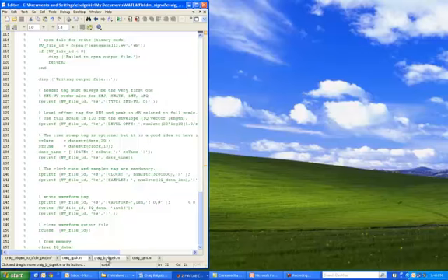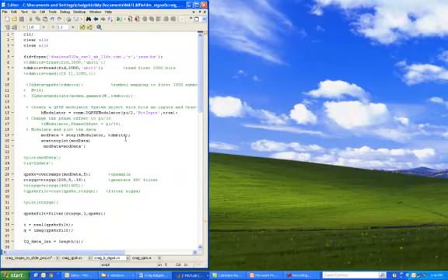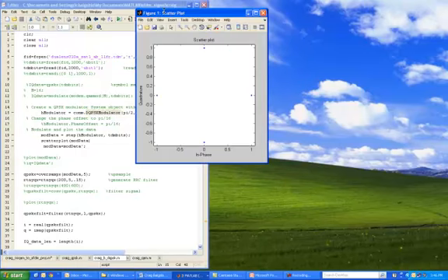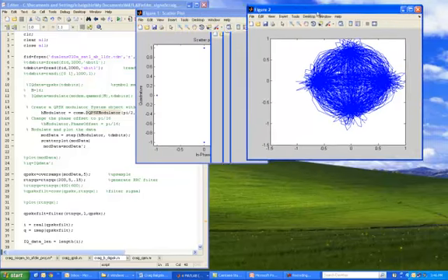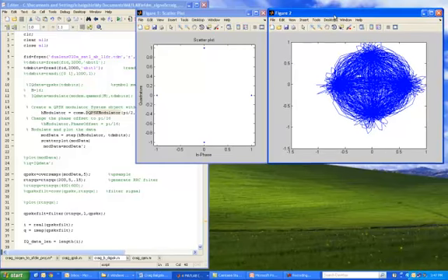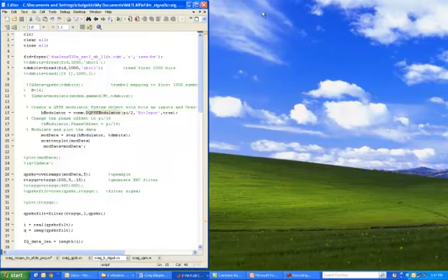Okay, so after I did the QPSK, I experimented with differential QPSK using MATLAB's differential QPSK modulator. Simulate that. So as you see, the scatter plot is a little different. It's phase shifted. Now the reason it's called differential is because it's looking at the difference in the QPSK symbols and then plotting a quadrant. So that's differential QPSK.